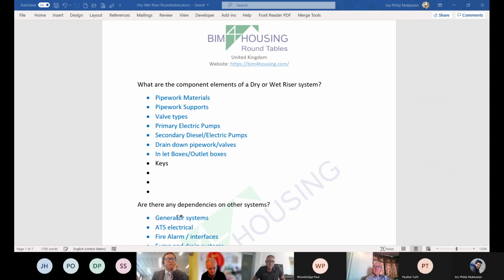The reason this is so important is that you used to be able to buy fire rated boxes, and you can't buy them anymore. What's been happening is that the fire strategy has been compartmenting the building this way, and the minute you open the door, you're into the level above. So it depends on where they are. They're quite a key component. You need to compartment this way with them, and it's been done that way. That's been a problem on a lot of jobs recently.